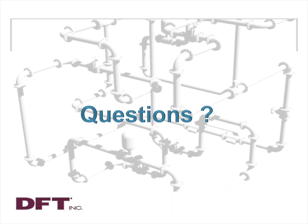Well, the answer is yes. You should be very concerned, because that sound is basically the sound of a hammer striking the metal that's inside the valve, and the hammer is the valve disc, and the metal that's being struck is the mechanical stop that's inside the valve. Over the course of time, that disc stop is going to get peened over and may cause the disc to get hung up, but more likely it's going to cause the hinge pin to wear and cause the disc to shift and no longer align with the seat, causing leakage when the flow stops. And this is all caused by low flow in the piping system.